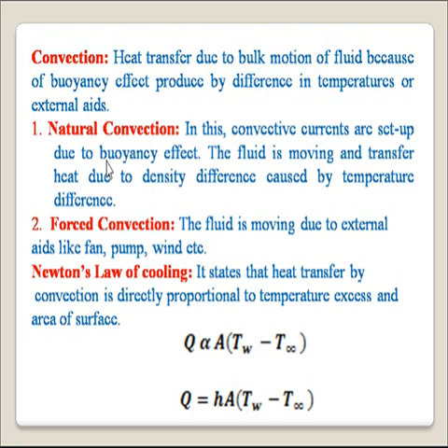Mathematically, Newton's law of cooling is given as heat transfer rate Q is directly proportional to surface area of plate or body into wall temperature minus fluid temperature. Introducing proportionality constant h, we have equation Q equal to hA (Tw minus T infinity), which gives the heat transfer by convection,